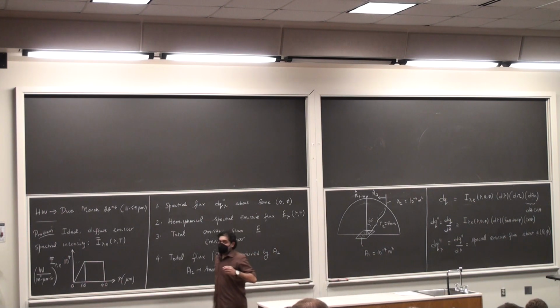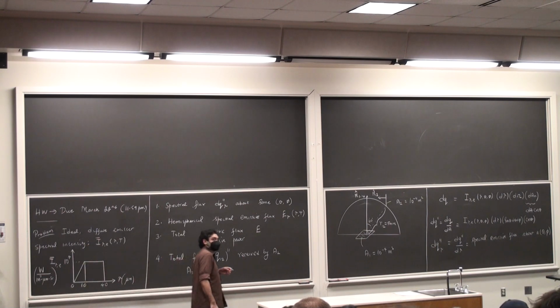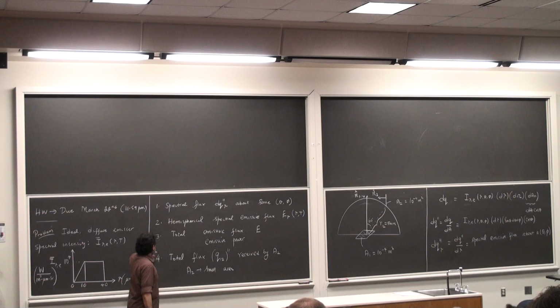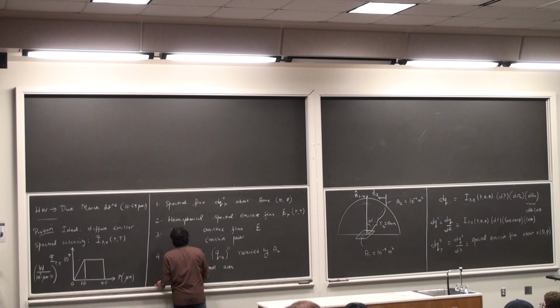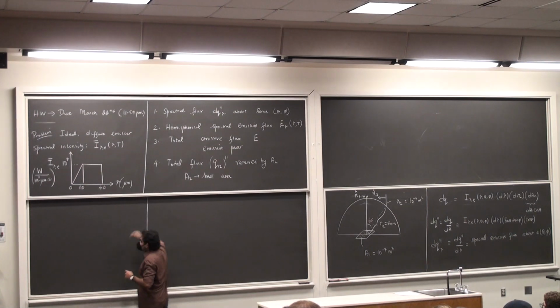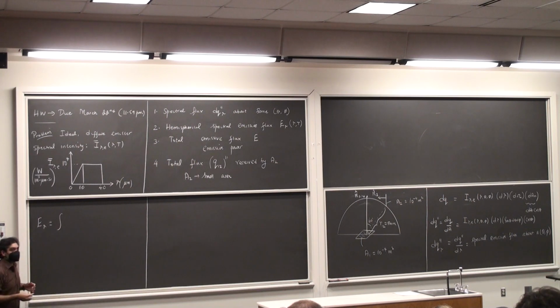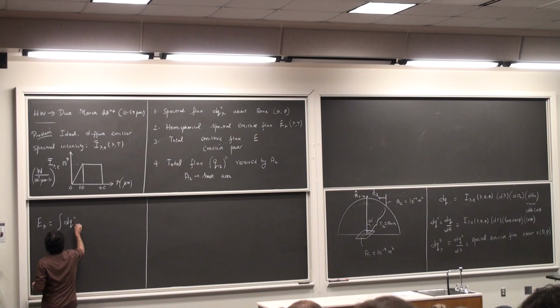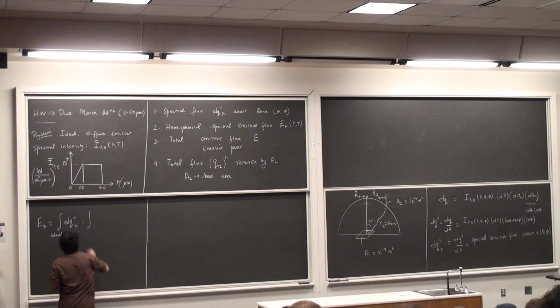And if I want the total spectral emissive flux, all I have to do is integrate over the angles d theta d phi. Go from 0 to 2 pi, go from 0 to pi by 2, and I get the second quantity here, which is the hemispherical spectral emissive flux, or the total spectral hemispherical emissive flux. So E lambda is now the integral of dq double prime lambda over all the directions.